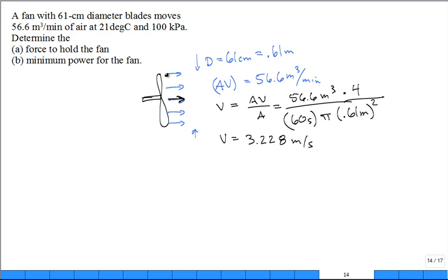Our control volume will be right across the outlet of the fan, and then sweeping back on the back side of the fan, a big, large, sweeping control volume, because the fan is drawing in air along a large area, but throwing it out straight ahead.